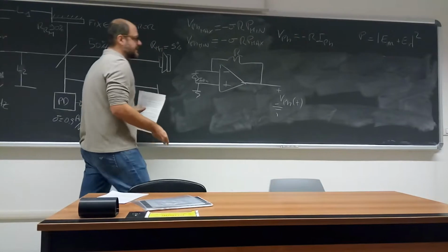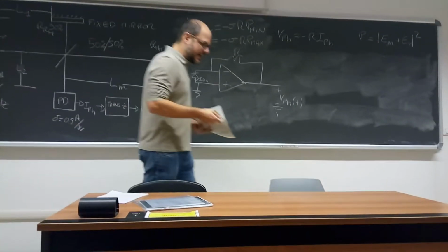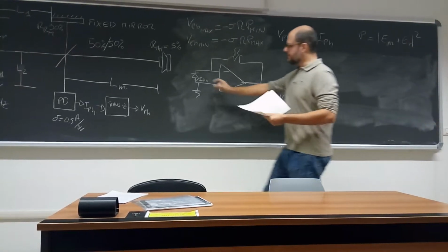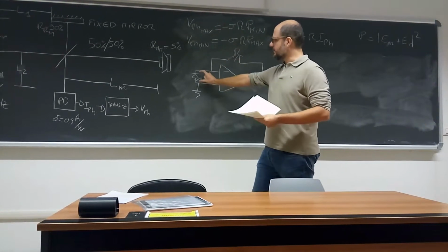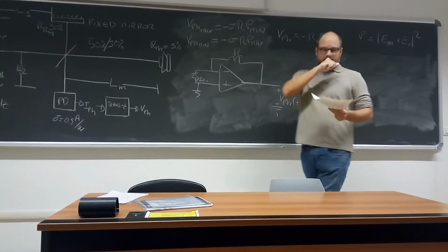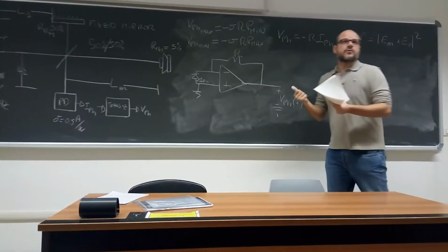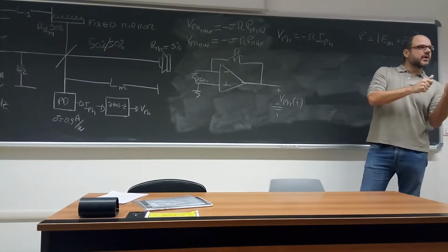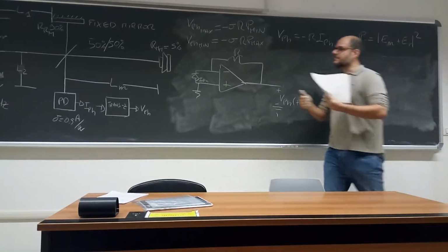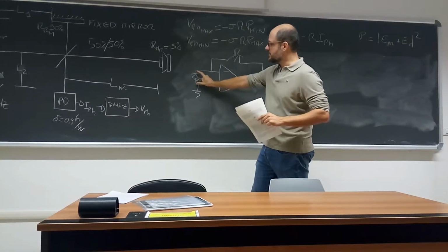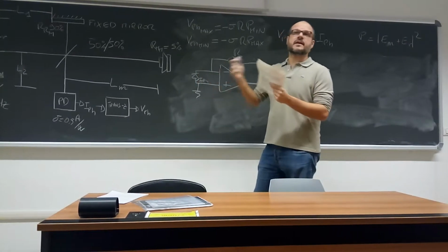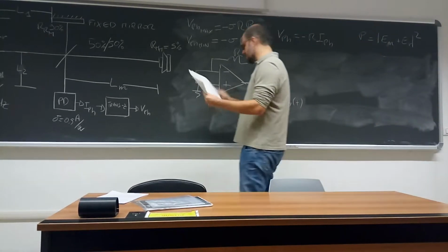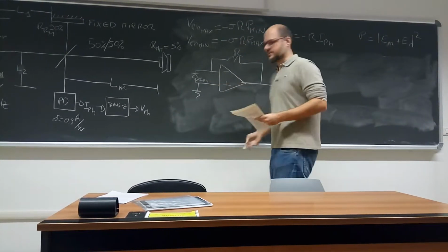Or this is a scheme that is, let's say, a dark current concealing scheme. Because of course, if the photodetector, in this case the photodiode, has 0 voltage between the anode and cathode, of course, the dark current is 0. Okay, so you have a good point, dark current is 0, but you have a drawback because this photodiode is not polarized in inverse voltage. Okay, so you just have to understand what is better for you, for your application.